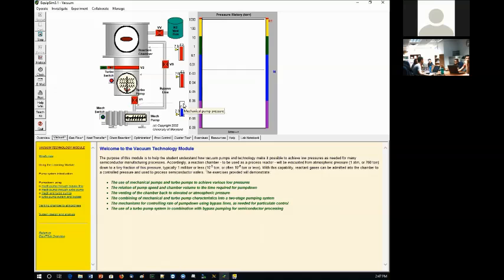So this is what we call the base pressure, and that's where we reached. You guys worked it out too? So we have now pumped down this bypass line, this little line. They have, just like electricity, their own conductance. So if the lines are small, their conductance is low. If the lines are large, their conductance is large, okay? That will determine the time it takes to pump down to the base pressure.